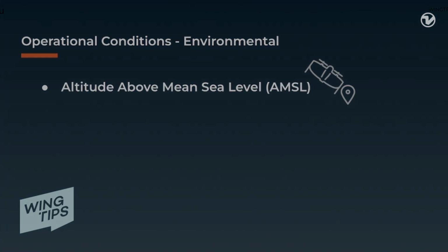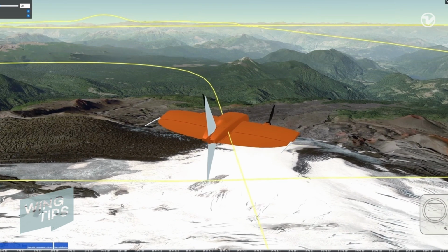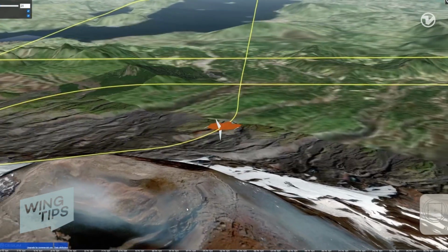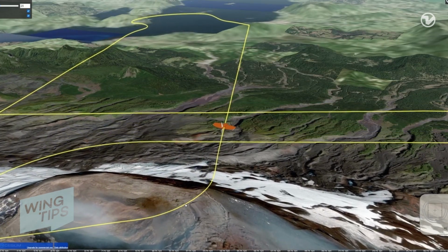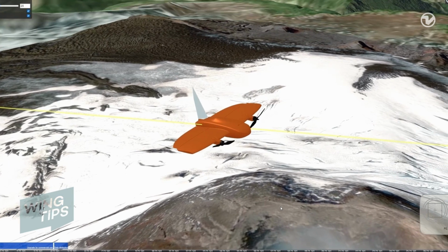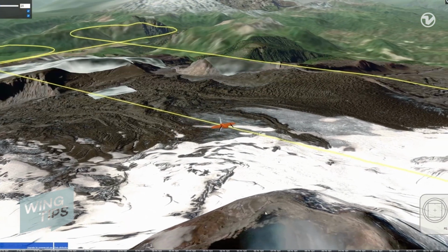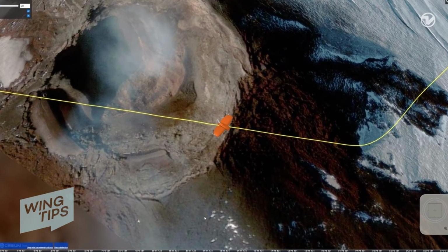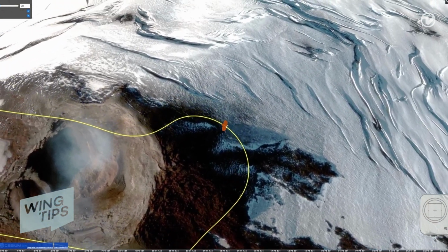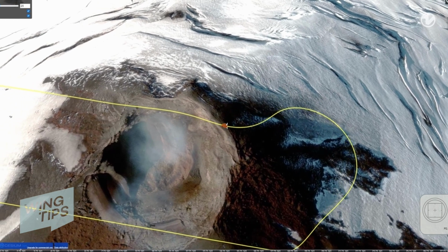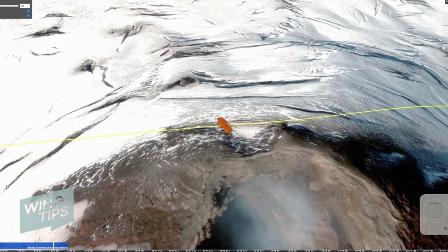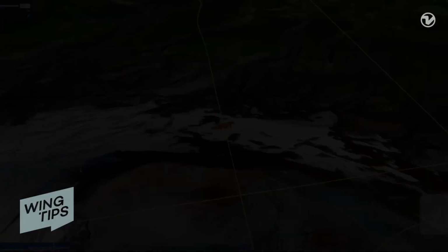In Wingtra's case, the WingtraOne can operate up to 16,400 feet AMSL when using our high-altitude propellers. But even so, its flight time is slightly reduced due to the thinner air. However, since the airspeed is slightly increased and the payload remains in spec, this is why it is possible to achieve a similar total coverage even with the reduced flight time.